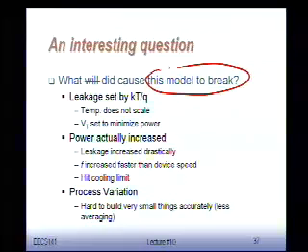If you keep on scaling the supply voltages, it turns out that this kT over q thing, the Boltzmann constant, isn't something that scales with technology, unfortunately. The charge of an electron doesn't scale with technology. And I haven't known the temperature to change that much either. Global warming might change it a bit. Temperature might go up gradually, but it's not going to go down. I know that for sure. So kT over q is a constant. And it turns out kT over q basically sets our leakage current.